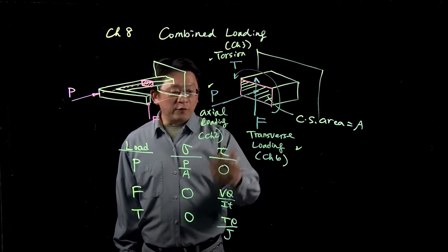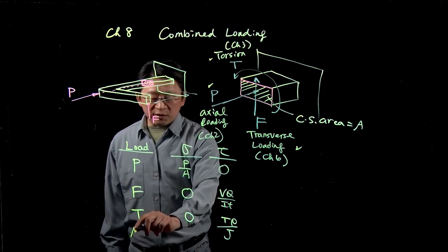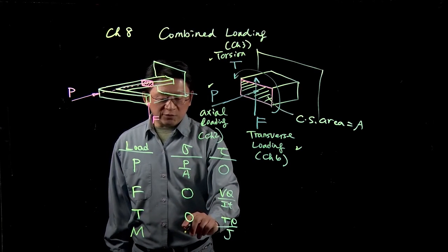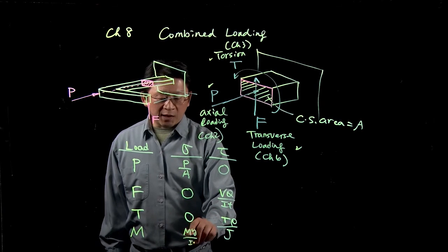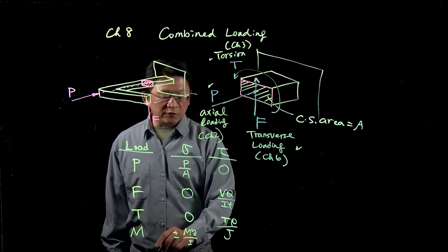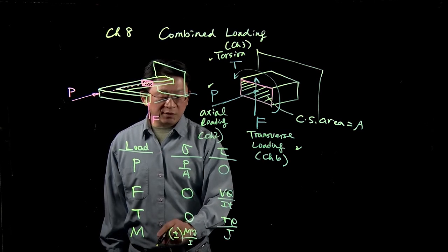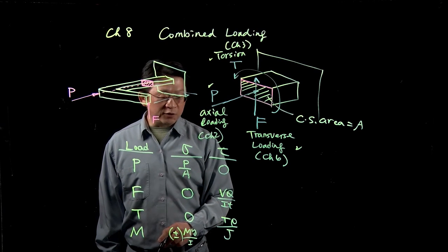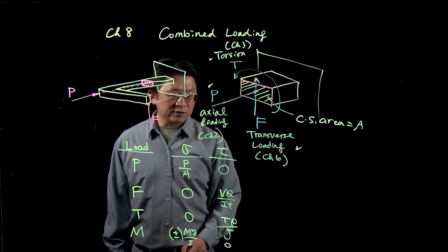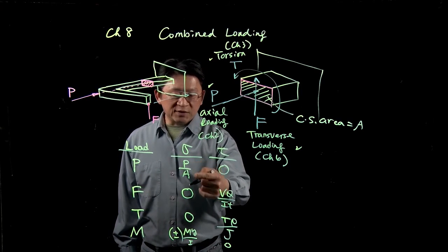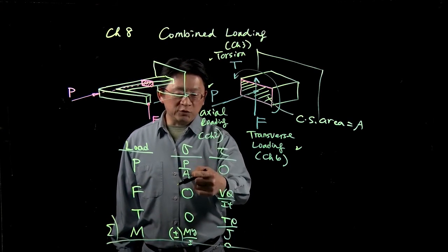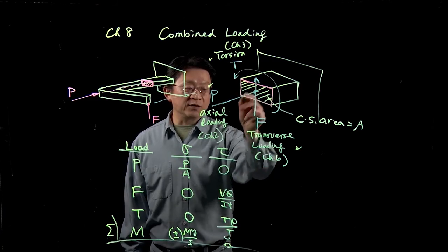Furthermore, for another example, if you have any bending reactions, then again the normal stress induced by bending is My over I, with a certain sign to indicate tension or negative to indicate compression. You can identify it individually for different problems. Again, corresponding to the bending moment, we expect no shear stress. So basically, by summing the terms together, you can get the distribution of the normal stress and shear stress around any point in this cross section.